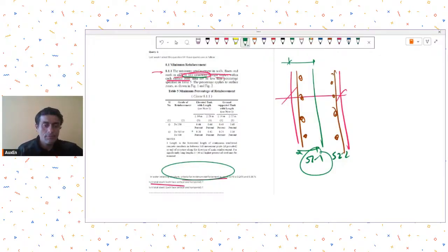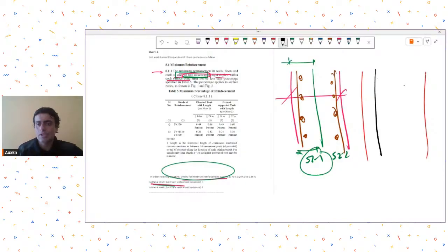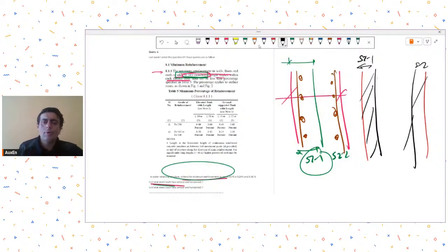Second question is, is it total steel? Yeah, so I just said it is not total steel in each of the two directions. Read this line over here, in each of the two directions. For thicker walls, the surface zones are taken as the zones on the edges only. So this is surface zone 1 and this is surface zone 2. So you calculate the reinforcement in this region at 0.24 or 0.36% and then provide it. So you just read the table carefully and read the figure that follows this table.